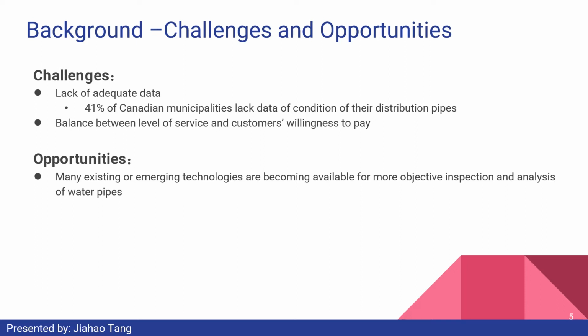Under such conditions, many municipalities over-rely on age-based assumptions, which frequently give misleading information. As a result, resources are often allocated to renew those assets that actually have remaining service life, while the real defects that require immediate repair or replacement are ignored.